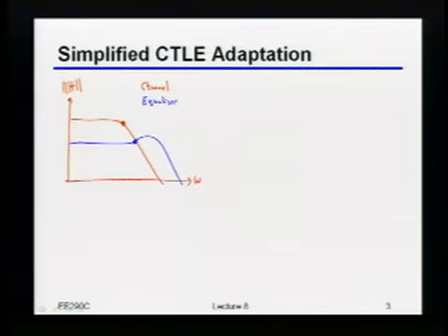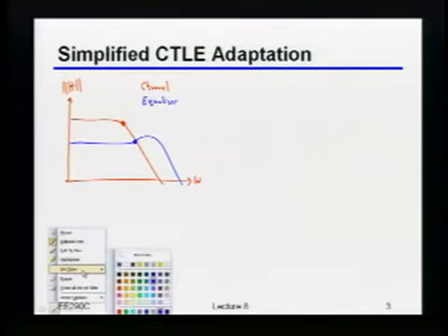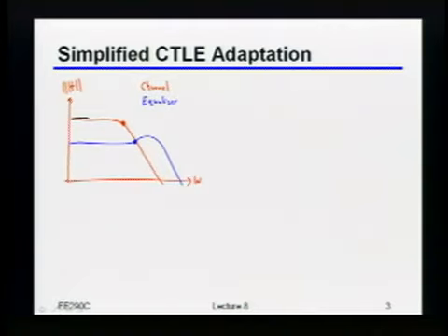Just roughly. I think Chintan kind of did it. Obviously down here it's flat. Then you hit the pole of the channel, then you hit the 0 of the equalizer. Actually, it'll be even faster than that because there are two poles there. It'll look something like this. So in other words, you're not equalizing enough, because clearly you've still got some low-pass characteristic in that channel.